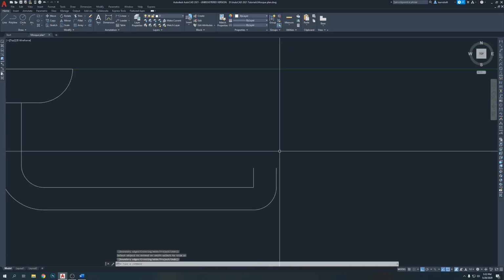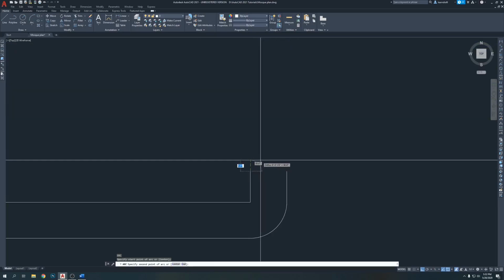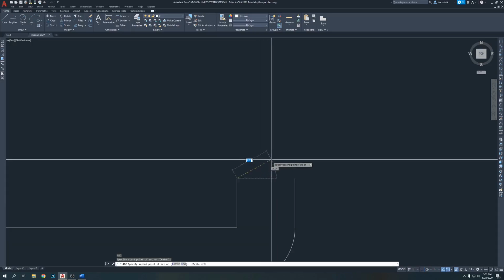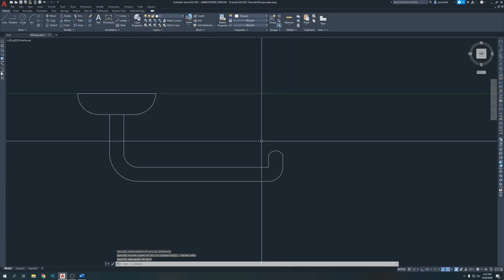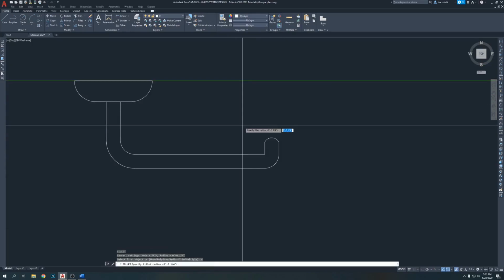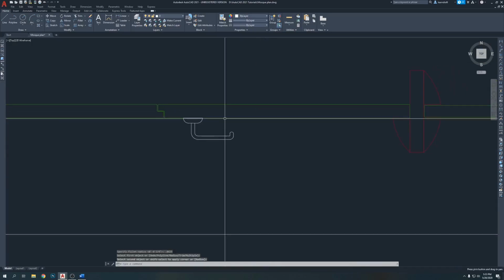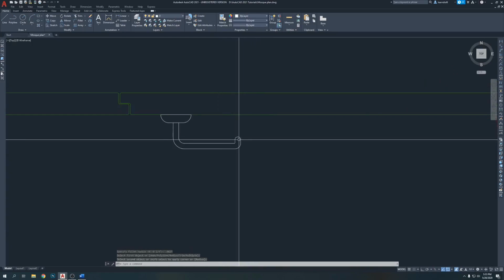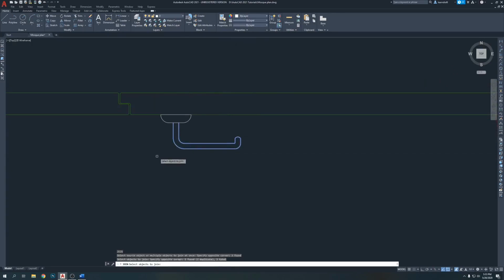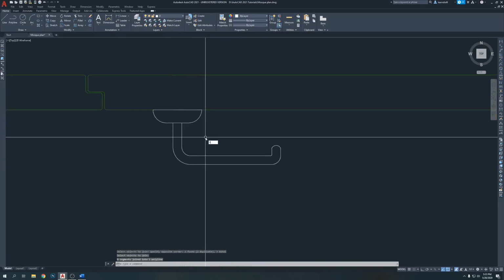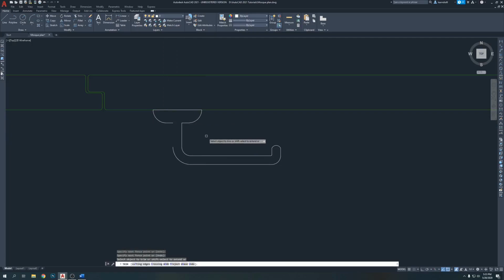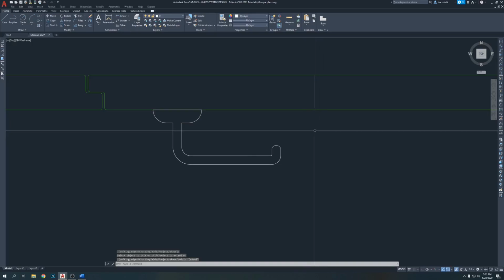Wow. Make a small, what is called, arc. So F8, fillet radius 0.0625, enter, which is 1/8 of 1/2. Okay. Yeah, join them together, so this frame is good. Actually, if I take this one out, how is it going to look? Looks good. No, join them together.